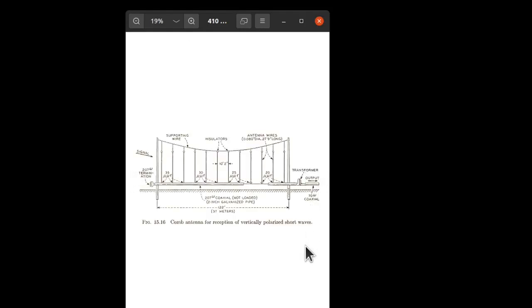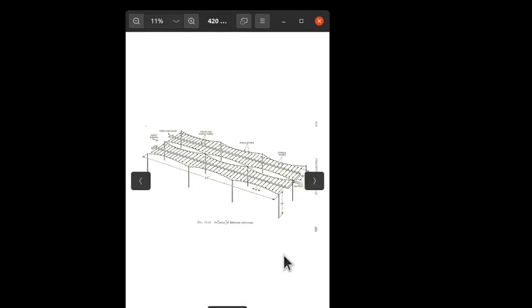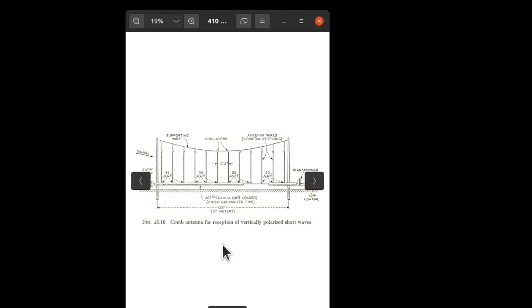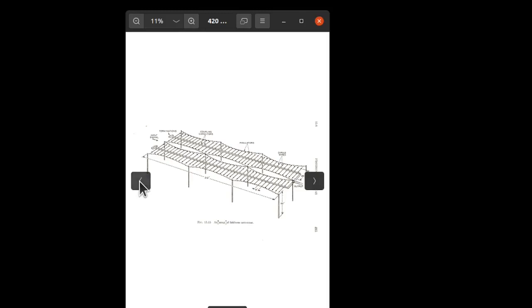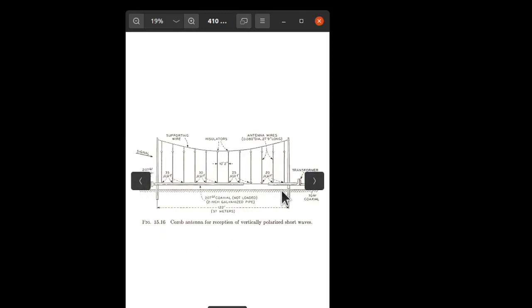In this particular, this is a half fishbone antenna. We've covered the fishbone before. I think it's the next, yeah. This is a pair of fishbone horizontal antennas in an array. This is the vertical. Okay, well, this is horizontally polarized. This is vertically polarized. And we're taking the feed from these drops down here along this line, which is, okay, this is being covered up a little.